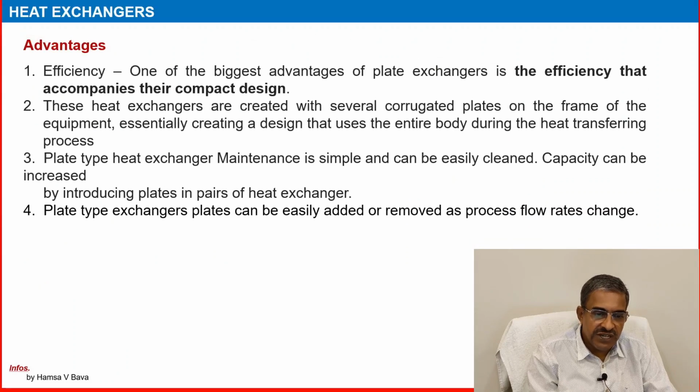Advantages: efficiency. One of the biggest advantages of plate heat exchangers is the efficiency that accompanies their compact design. These heat exchangers are created with several corrugated plates on the frame of the equipment, essentially creating a design that uses the entire body during the heat transferring process. Plate type heat exchanger maintenance is simple and can be easily cleaned. Capacity can be increased by introducing plates in pairs of the heat exchanger.